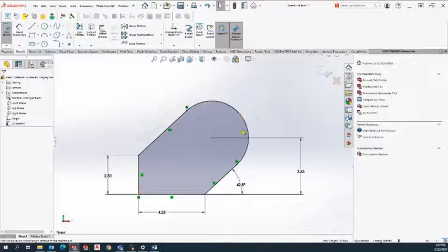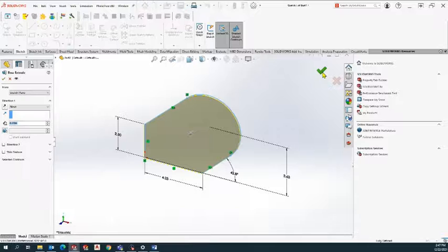So now you start to see that the drawing has been completely locked in. That drawing now will not move for any reason. And this, when you work in SolidWorks, is a fully constrained drawing. That is a term that they use, and you'll see that a lot when you're working in SolidWorks. So once you've completed your drawing and everything has been fully constrained, you can confirm the drawing by clicking on this icon up here. That's going to confirm and close that portion out.